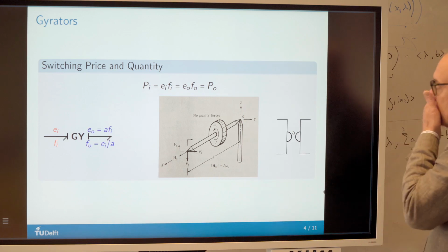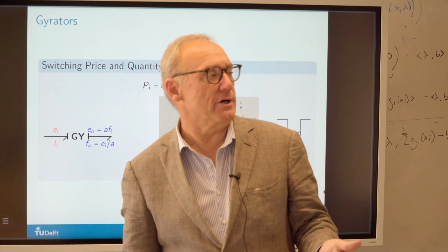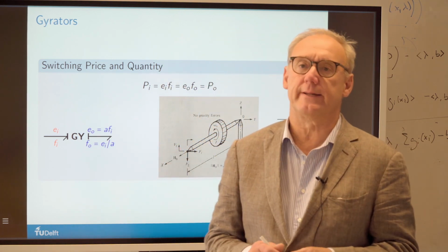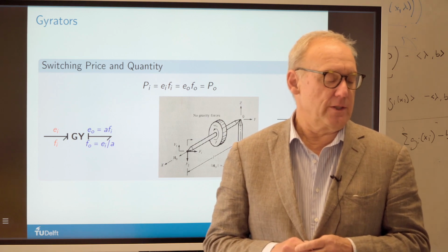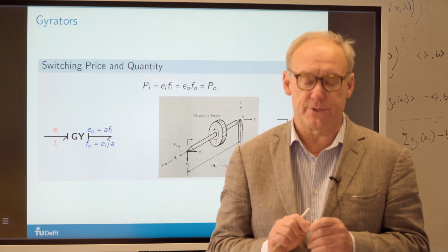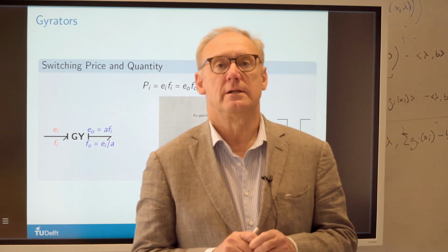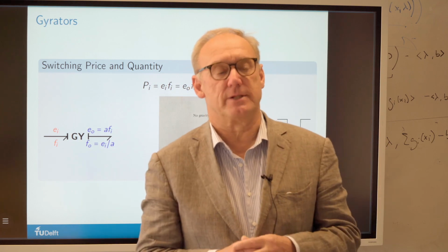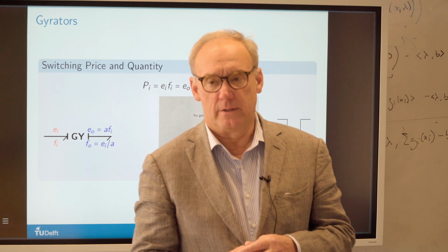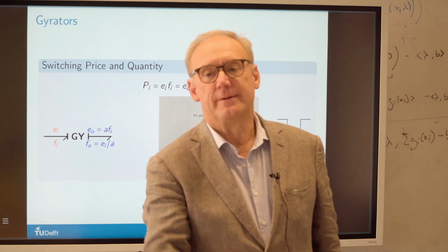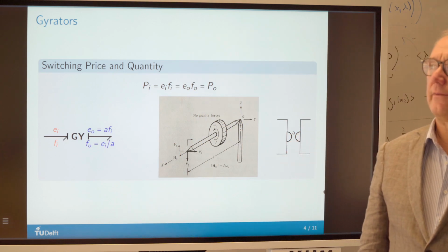But you would think that with I, C, R, the two junctions and transformers are basically there. In a sense, you are, because I think you can basically make every circuit this way. But there's a shortcut to get the full range of possible linear circuits. No, it's the other way around. You can make everything with gyrators because two gyrators is a transformer. That's right.